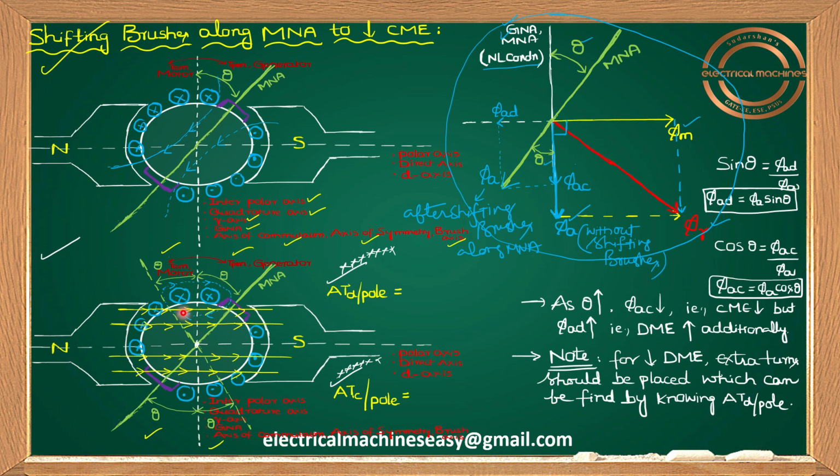They see the main flux, the yellow color, going from left to right, okay. But instead of seeing the armature flux in this magnetic region, they are seeing it here. Don't see this one, because here we don't have any main flux. We have to see the direction of armature flux where the main flux is present. In this region the main flux is there. Try to see whether your blue color arrow marks are opposing the main flux or aiding the main flux.